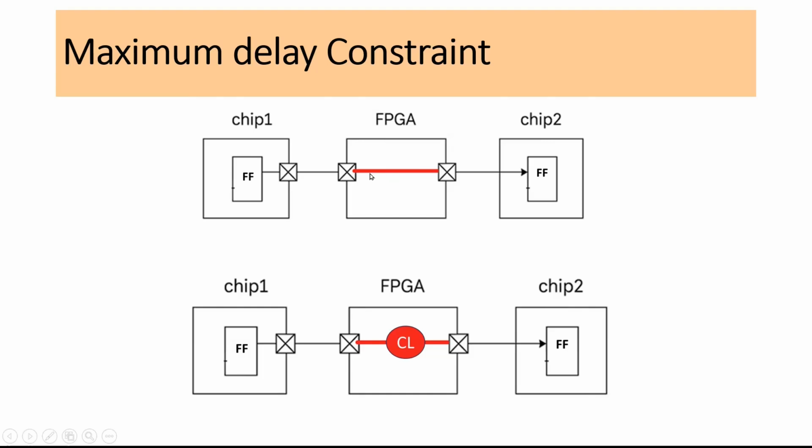One type of path is which is just a net delay. There is no combinational logic also in between. Other type of path is when from input to output there is a combinational logic in between, but there is no sequential element. In a nutshell, in this category of path, I want to say that there is only a single bit that is traveling from input port to the output port. It is not a data bus.